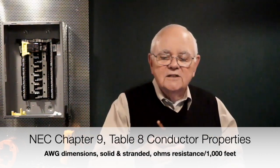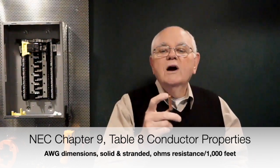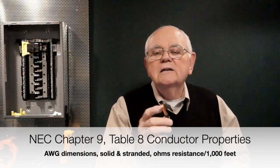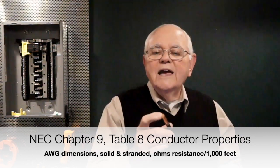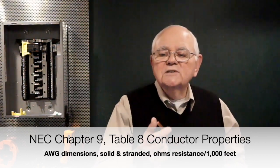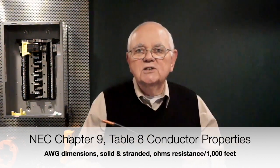This is a stranded conductor, 2 AWG, so it's required to be stranded. Chapter 9, Table 8 will tell us how many strands of wire we have, the physical dimensions of each strand, and the total overall dimensions of this copper conductor. Chapter 9, Table 8 doesn't address the insulation at all.